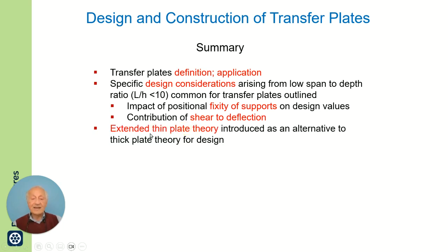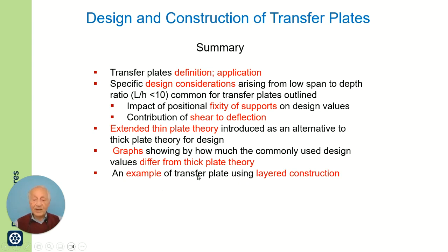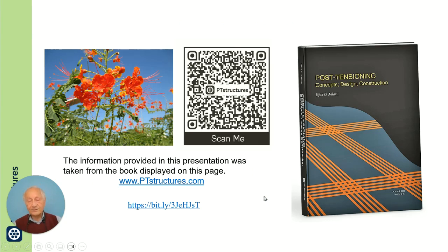Then I talked about extended thin plate theory for transfer plates. I showed a graph which talks about thick plate and thin plate deformation and bending moment. I went through an example of a transfer plate using layered construction and gave some construction views, with the focus on tendon layout.